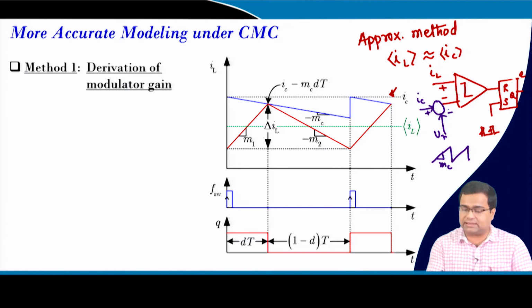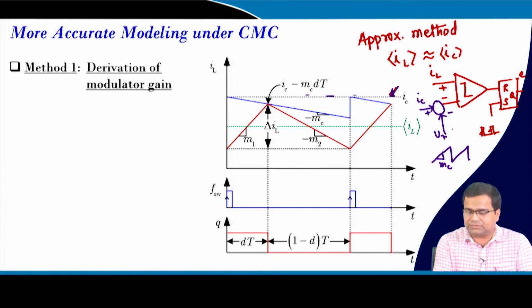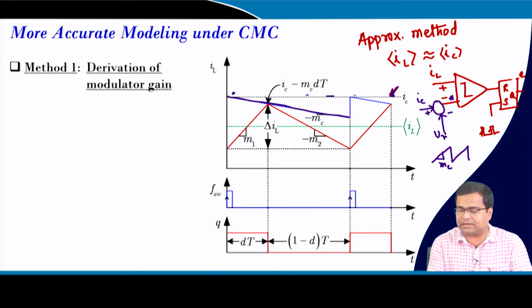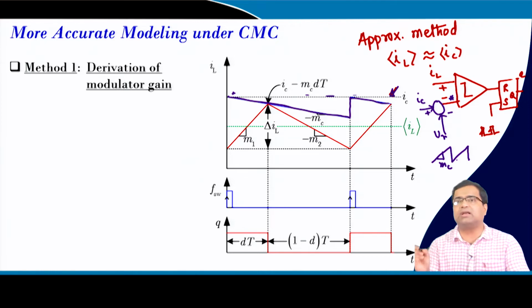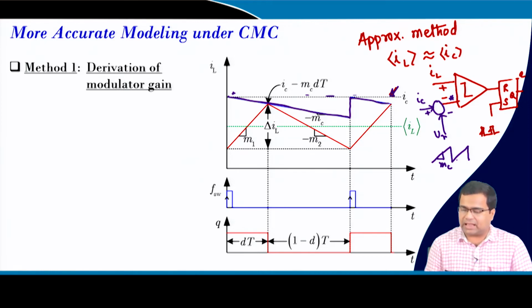In this case the waveform shows a dotted line which is the pure control current. Now, we have subtracted the ramp current. So, the actual current reference, this waveform, is going down because the ramp is subtracted, so its slope will be falling, but the actual ramp is a rising slope. And this is compared to the inductor current. You can see the inductor current is rising. When it hits the peak current, then the switch turns off.